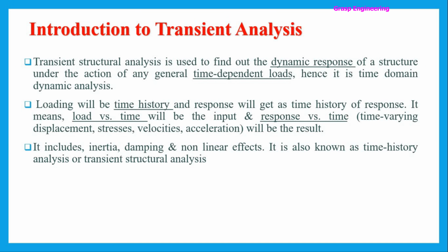When we talk about transient simulation, it includes inertia, damping, and we can also include the non-linear effects. It is also known as time history analysis or transient structural analysis. So you should not be confused by transient dynamic or transient structural; both are the same. As mentioned here, it includes non-linear effects. It means that if your model consists of frictional contact or material or geometric non-linearity, you are able to analyze that effect with the help of transient structural simulation.